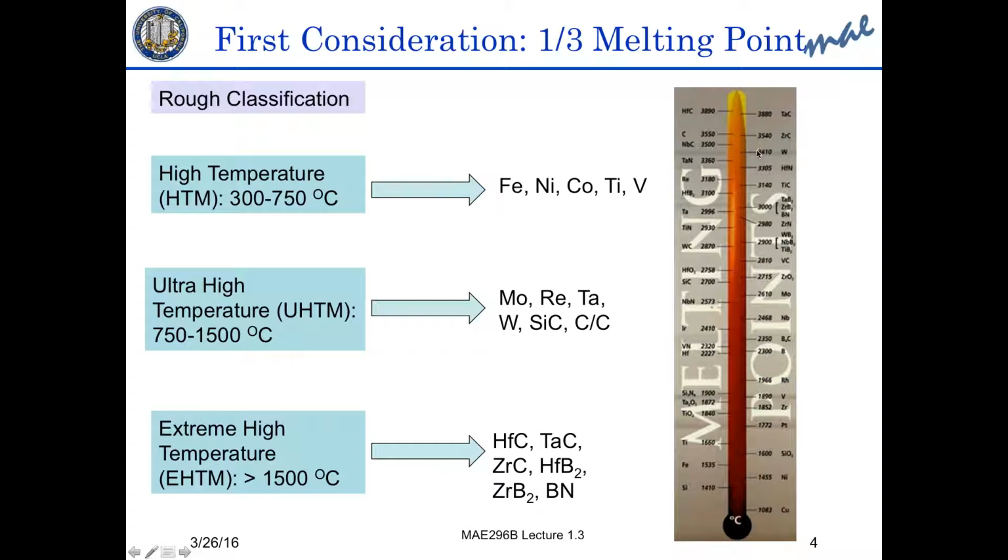And then you start alternating between metals. We call them refractory metals, like tungsten, rhenium, tantalum, and then molybdenum. So these are the refractory metals. And then in between you find carbides, titanium carbides, niobium carbides, and tantalum, and then nitrides come in. So you have borides, carbides, and nitrides as the top ceramic materials of the refractories. So you can have tantalum, zirconium, boron, or the refractory metals themselves will be a group.